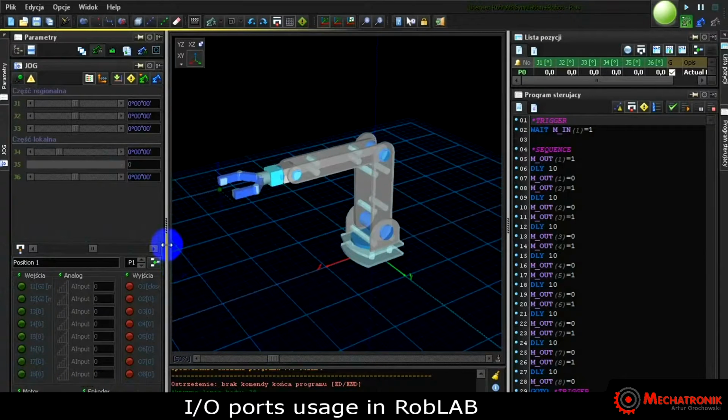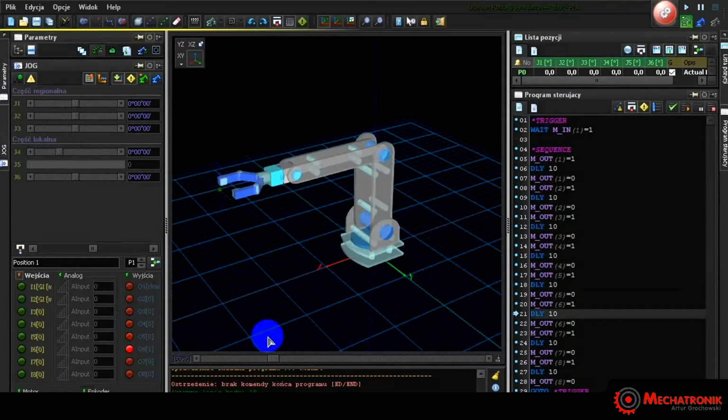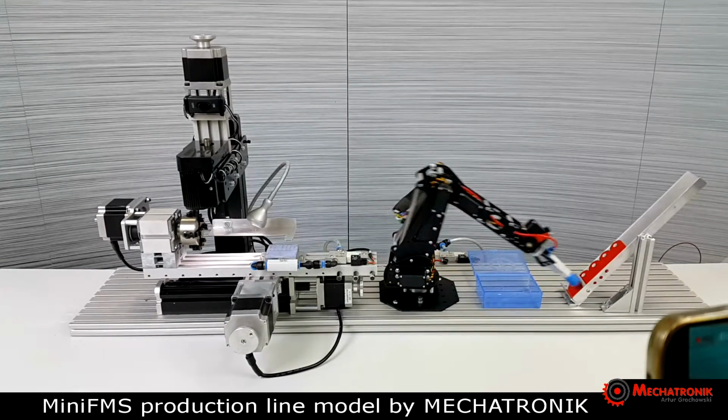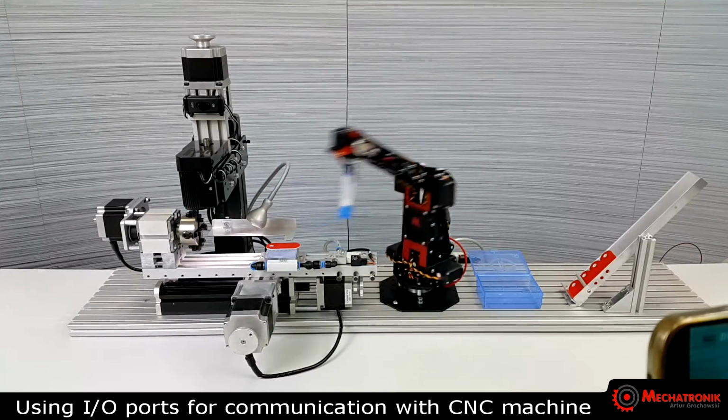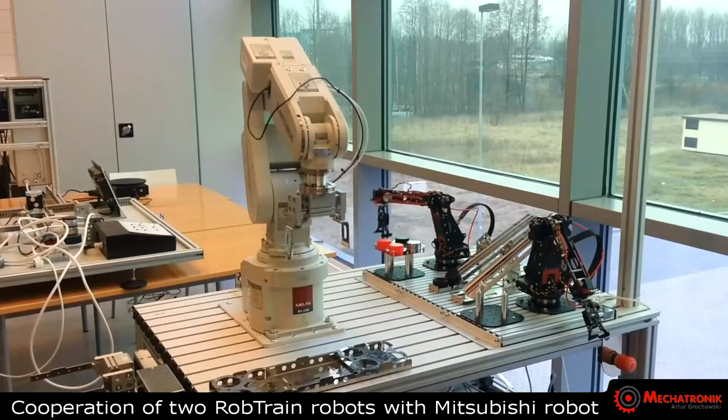The robot's controller and the application itself have an additional I/O module that can be used both from the software level and manually. This additional functionality of the application enables not only controlling the robot's arms, but also cooperation between the robot and actuators, signaling devices, such as transmitters, valves, motors, push buttons, indicator lights, and any industrial sensors. This functionality of the application, together with the control system and the robot, allowed us to build and control a MiniFMS production line with a CNC milling machine, as well as the system where two RobTrain robots work along with an industrial Mitsubishi robot.